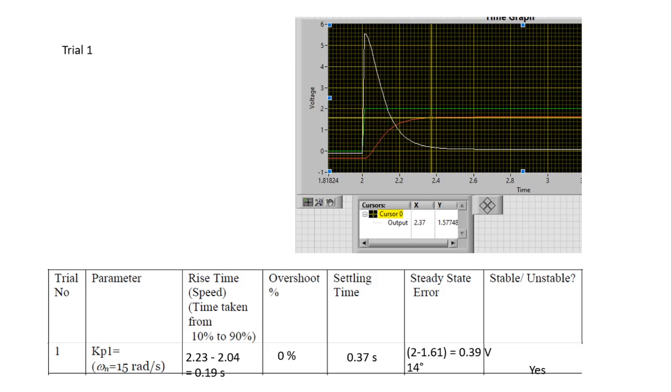I think I should just do it in my head instead of using a calculator. So that's 1.8, and I want the 90% of it, so that's 1.62. That's measured from the very bottom, which is negative 0.2. So subtract 0.2, 1.42. So I found out when it hits 1.42. I said it's about 2.23 seconds.